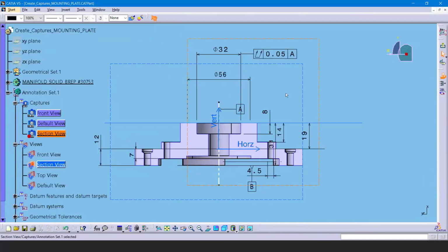But let's say that I want to get a little bit fancier. You can see that it's cutting through the model, and it's just displaying it as the default gray cross-section because that's what my part model is. So let's have CATIA show us the actual hatching lines. You can also do dots or an image.